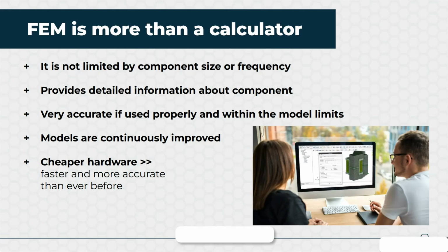And low frequency here doesn't mean that we are limited to 50 hertz. It just means that the size of your component has to be much smaller than the wavelength that you are solving. So for example, a small component at very high frequency will be equivalent to a very large component at lower frequency. But what you will not be able to solve is a large component at gigahertz frequencies. For that you will need a wave formulation, a different electromagnetic formulation that describes electromagnetic field propagation as a wave.